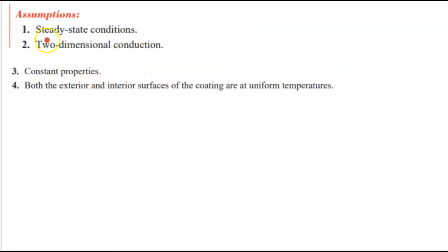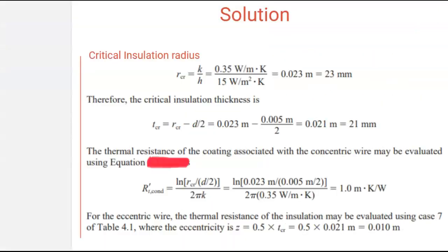Now we need to make assumptions. Steady state condition applies, and two-dimensional conduction is happening, not three-dimensional. We assume constant properties throughout the material. Both the exterior and the interior surface of the coating are at uniform temperature.